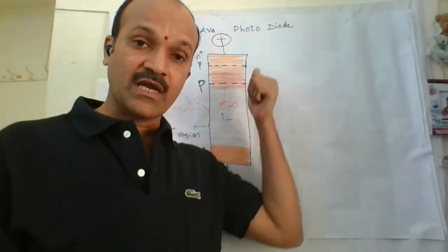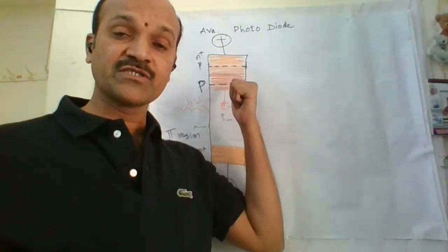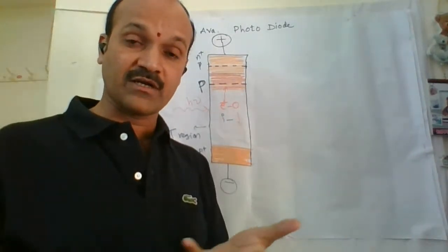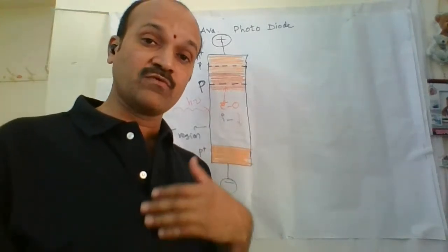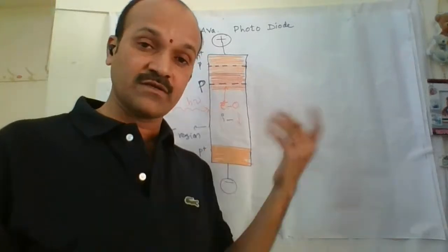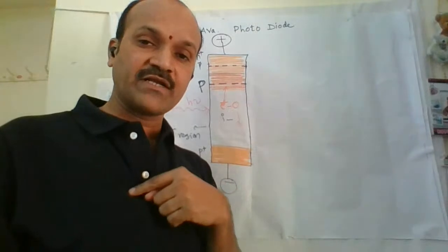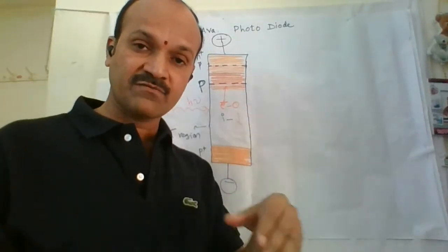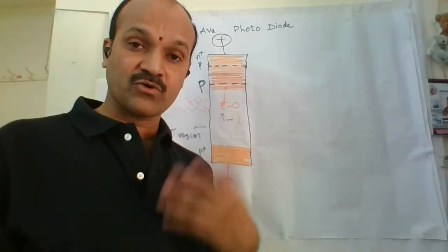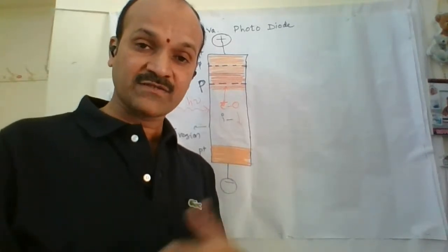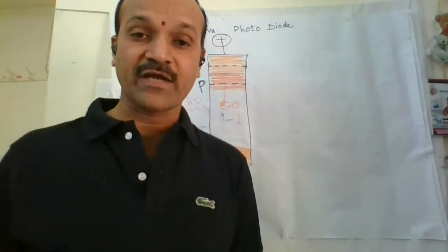And the field in the PN region is maximum, a higher electric field. These saturated electrons enter that region, move with maximum velocities, and collide with lattice atoms and other electrons. When one collides with an atom, an electron comes out from that atom: ionization. Like that, many electron-hole pairs will be formed. So that amplification phenomenon is known as impact ionization.